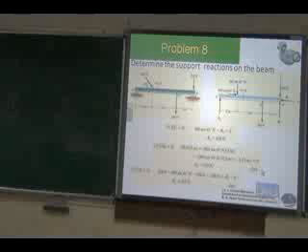It is not bolted, so if a force is applied, if it is trying to move in x direction, it can be moved. It can be moved in x direction, but it cannot move in y direction because the flat surface and the ground are in contact. So only AY is there at point A, but at point B, since it is fixed, AY is there, BY is the reaction. Two reactions. Point A has one reaction, point B has two reactions.